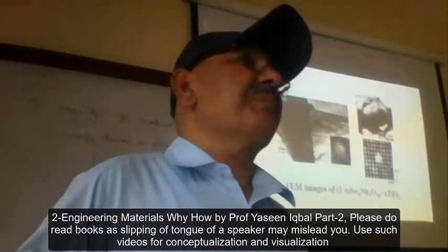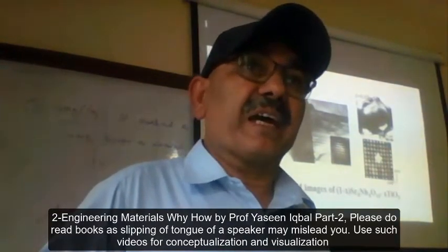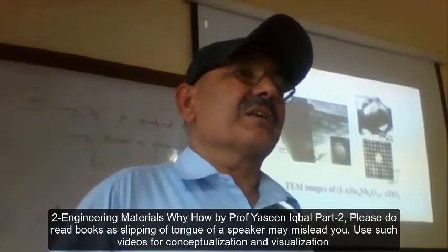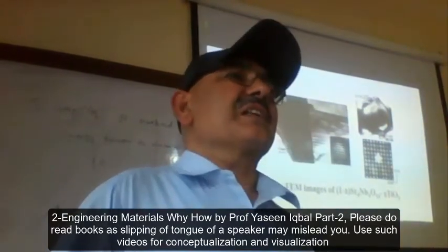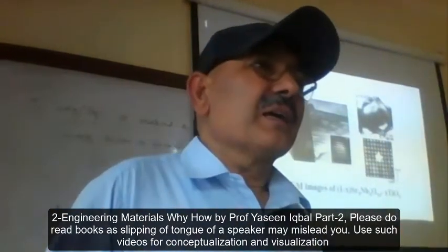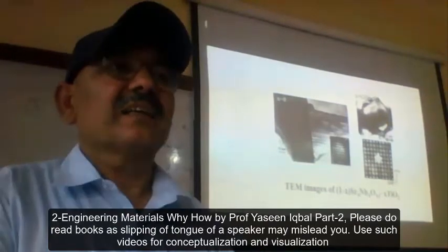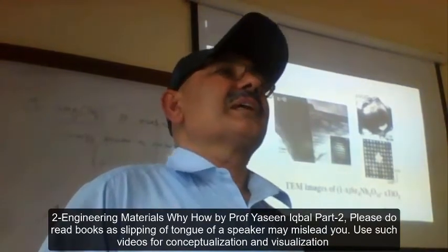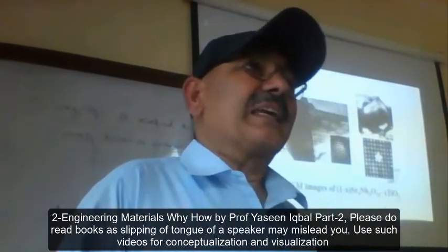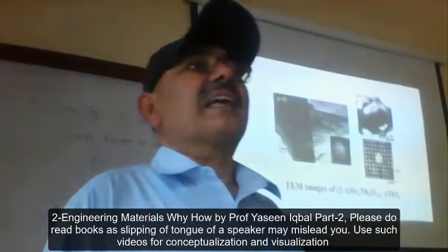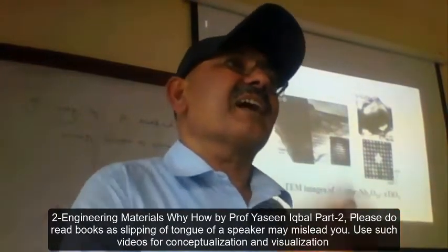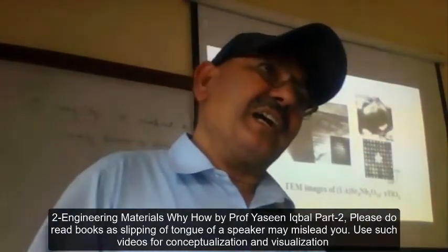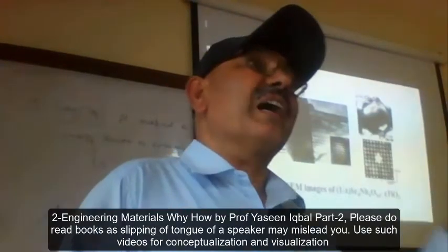Are the grains densely packed, are they scattered, is the structure contiguous, does the structure appear loose, is the grain size non-uniform, is the grain size uniform, are grains elongated, needle-like, lath-like, rectangular, cubic, cuboidal, ellipsoids, spherical, spheroidal.